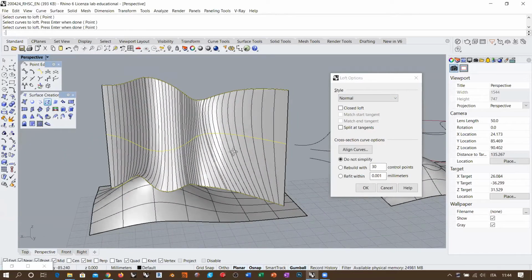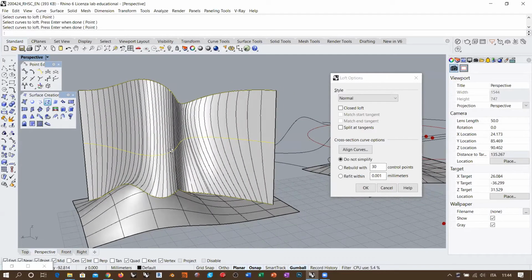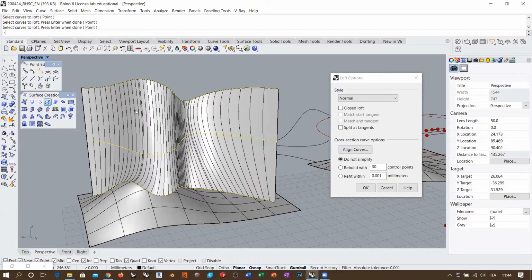You see that having a more regular topology is not enough for regularizing the vertical aspect of this isocurve. Why? Because the lower curve has a constant speed now, because the control points were redistributed in an even way along the path. The knot vector is uniform knot vector, and these two features make the speed of the curve constant. But here we have two different topologies from the lower one, and the speed is not exactly the same. So it's the speed that makes the isocurves bend along the path.